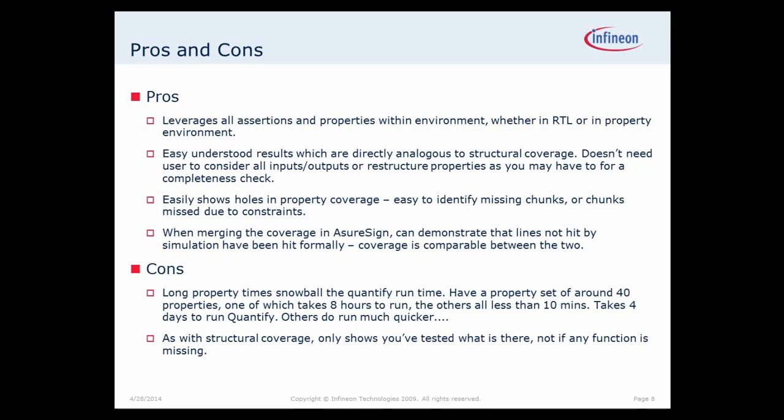I haven't used the latest Certitude flow in their integration with formal tools, but what we did previously was take their formally instrumented code and run it through OneSpin, switching on the individual faults. And because there are multiple faults per line from Certitude on the more complex lines, it was typically taking a lot longer to prove.